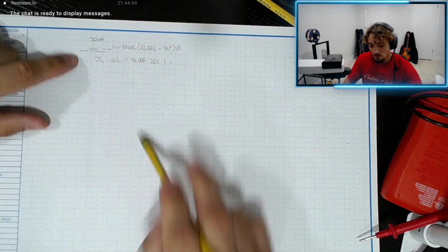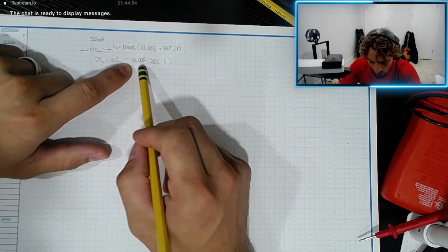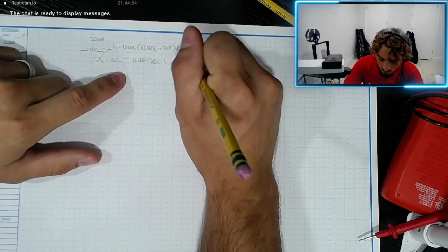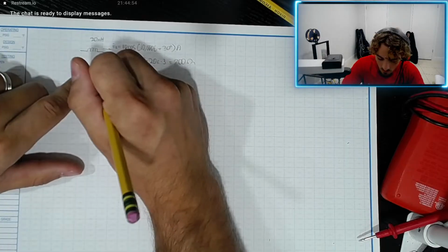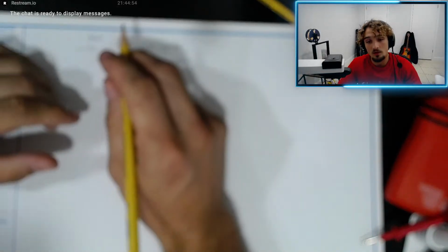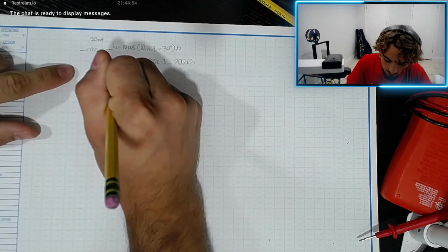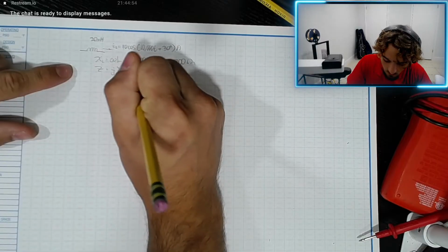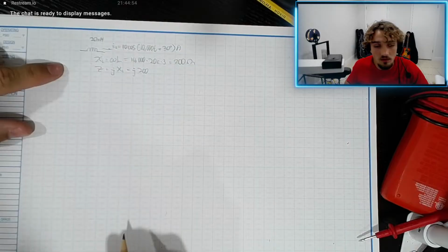Well, 10 e to the 3, 20 times 10 is 200. So 200 ohms, right? It's a reactance, X_L. And then it asks for the impedance of the inductor. The impedance Z equals jX_L equals j200. Right, let's just put it like that.